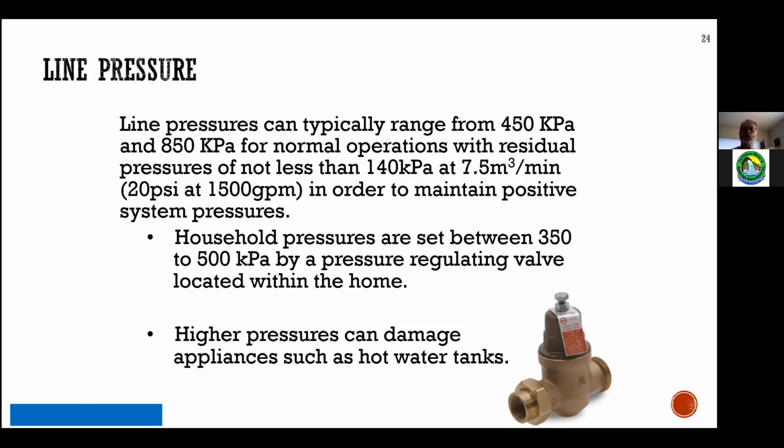And then once we start moving water through the system, and think about it, systems are always moving. Once you've filled a reservoir, there's demand, and so water is constantly moving. Well, how much is the head loss? How much energy are we losing? There's a picture of a regulator, which may be on the inlet side where a customer's connection either connects to the city at the curb stop or in the house, and basically is set to, if the city is delivering 60 psi, you might be dropping it down to 50 psi, that sort of thing, just to protect the internal plumbing.